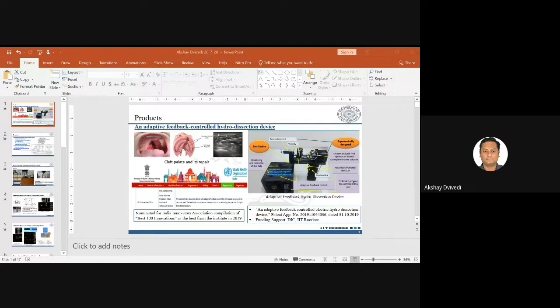In fact, if you look here, I have my nascent tool, which is of 600 micrometer diameter. When you work with simple electrochemical discharge machining, the film thickness is 1050 micrometer. When you add ultrasonic vibration to it at 5% power rating, this implies, let's say if you have a 500-watt machine and you are using just 5% of that, that is only 50 watt, your film is reduced from 1050 to 840 micrometer. At 10%, it is reduced to 780 micrometer, and so on.